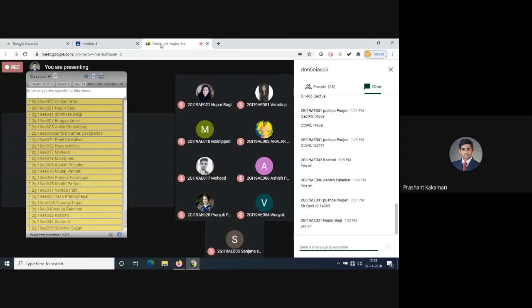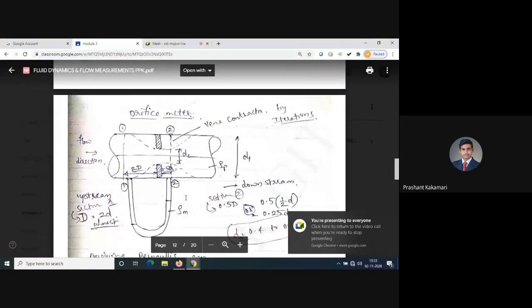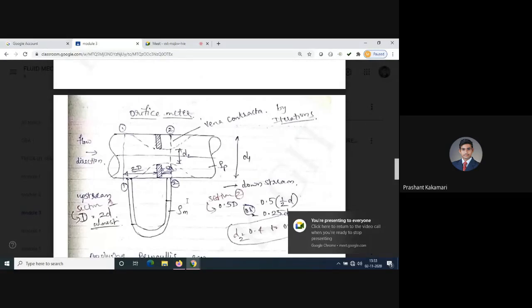So I think by going through these two Venturimeter problems, with corrections and without corrections, you might have understood using the formulas and converting all the values. Okay, that also adds to our understanding. Now coming back to the derivation of this orifice meter. As I told you, the derivation steps are similar for orifice and Venturimeter. Also, you can recall the equation you used in the lab. So keeping that in mind, we can again apply Bernoulli's equation and the continuity equation, and we will focus on what extra term is introduced in this derivation.